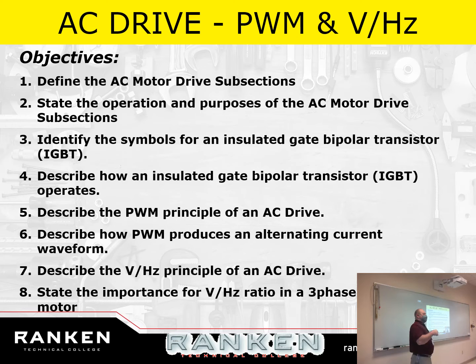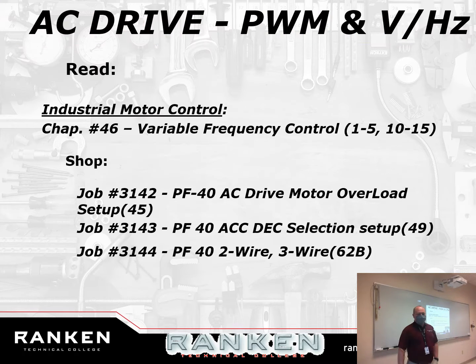But if you don't have the volts over Hertz ratio, it would cause that. So like, if you're not running the drive in volts over Hertz, if you're running it, say, in vector mode, where you just turn it on and run it at a specific speed, no matter what the load is, you could have this higher current on it and start giving nuisance tripping. So, that's what we're going to talk about.